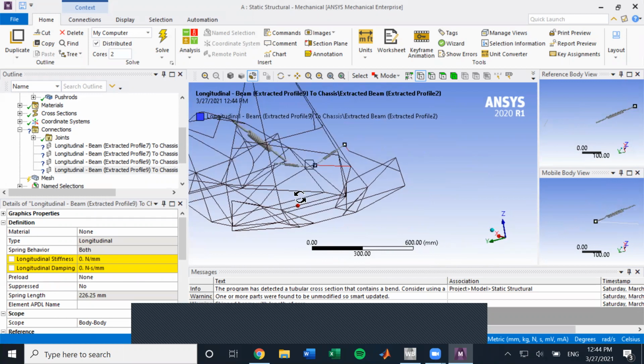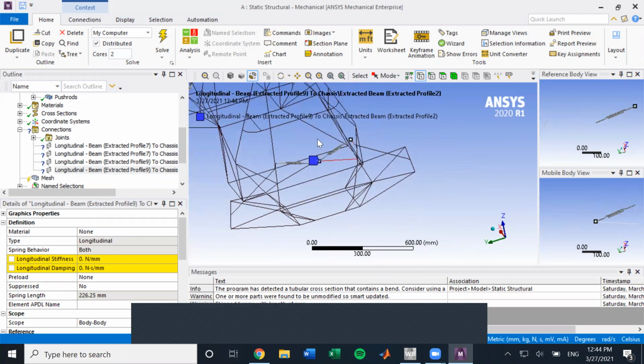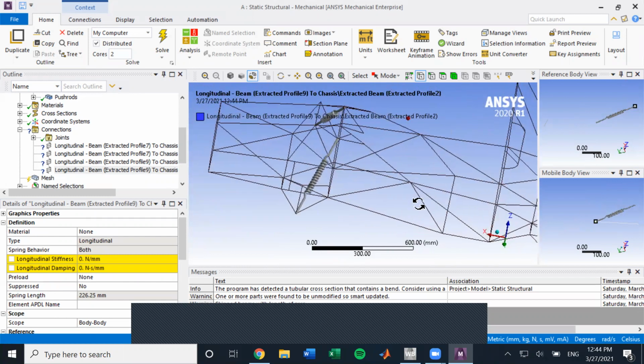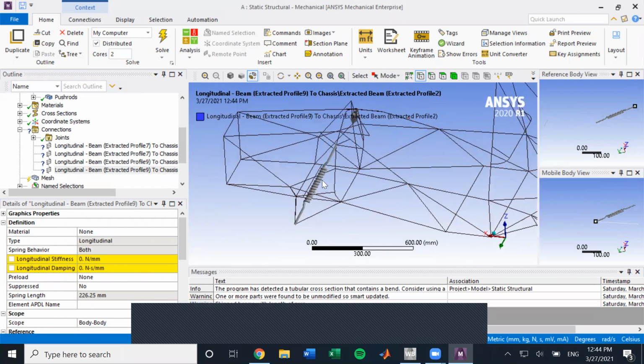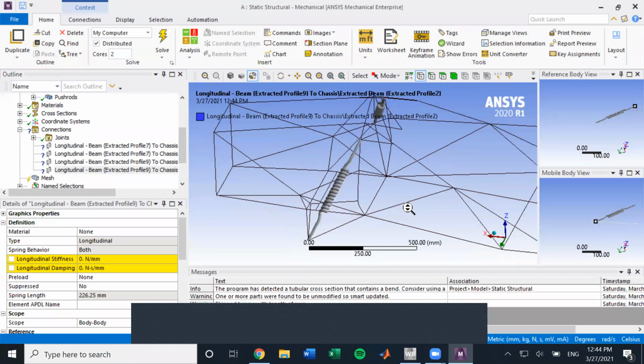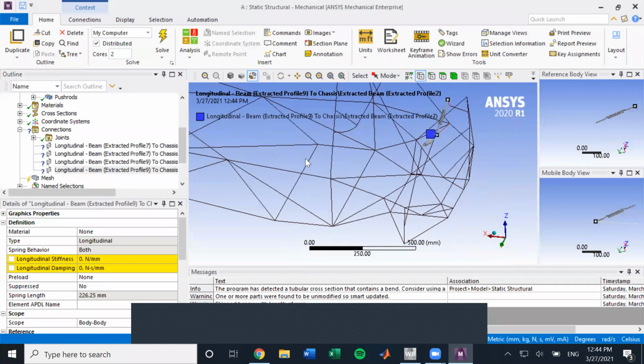Perfect. So this is what our springs will look like. The rear is more accurate just because it has the whole rocker pushrod shock interaction. The front is a little bit less accurate, but I talked to the suspension lead and learned that, just looking at the load path from where the pushrod, rocker and shock would interact, the rocker is mainly used in the front for clearance issues, whereas the rocker in the rear is actually just to change the load path.